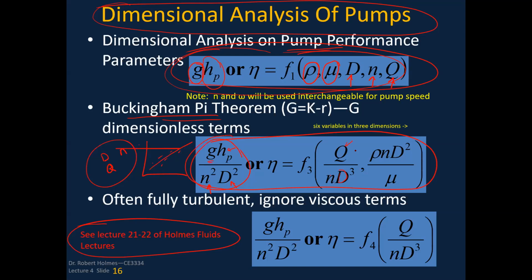This makes this dimensionless. This is now my diameter. This is my dynamic viscosity. This is my speed. This is my density of the fluid. These are all non-dimensional or dimensionless aspects. This is a term here that's dominated because of the dynamic viscosity. We think of that as a viscous type of term.